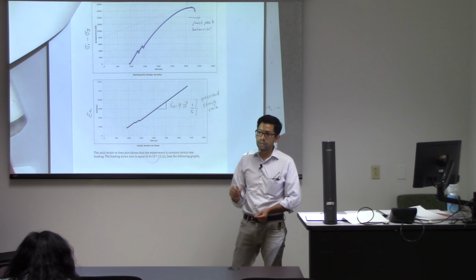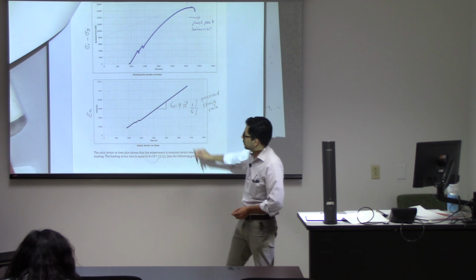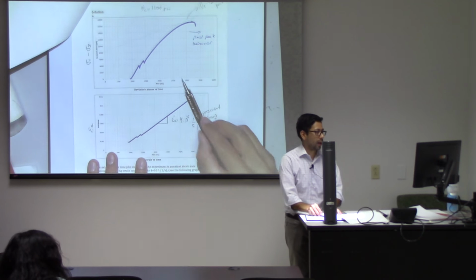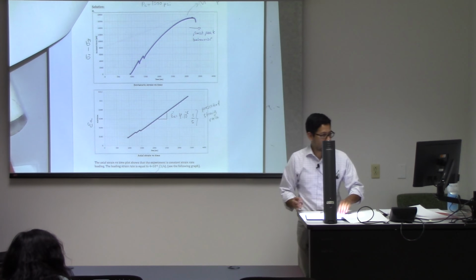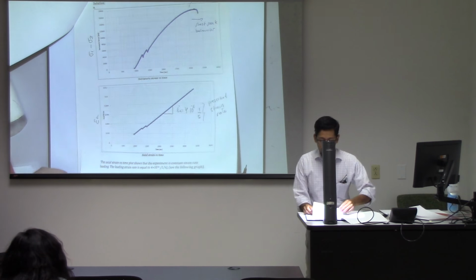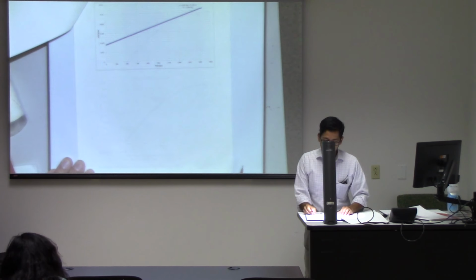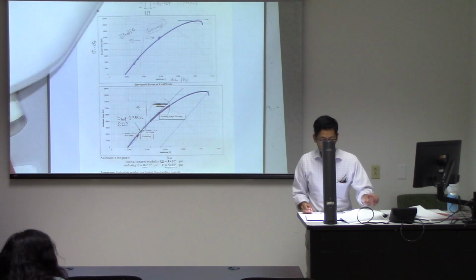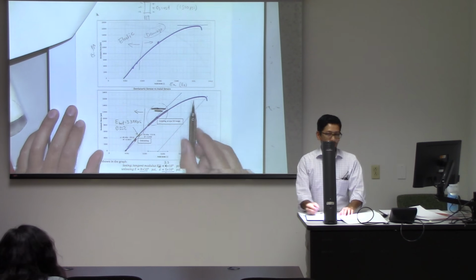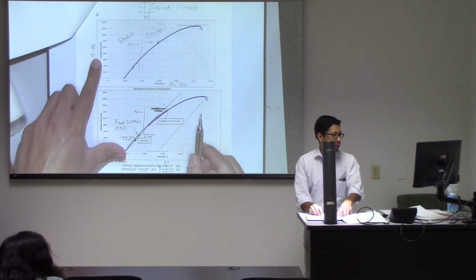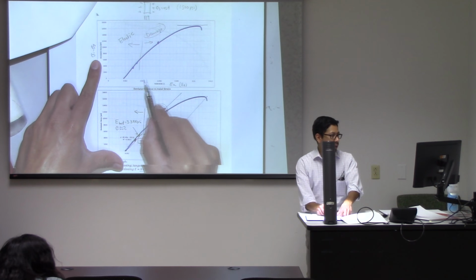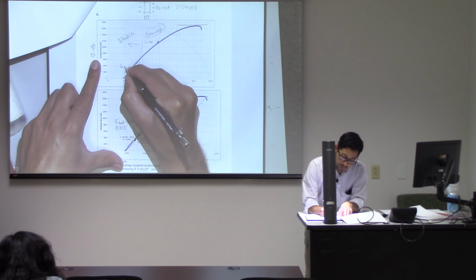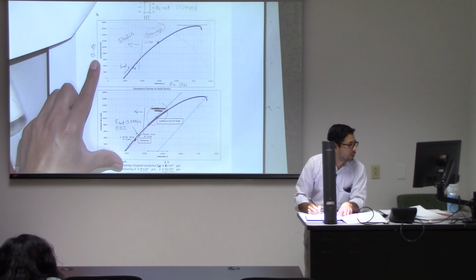But something very important for you to remember is that in many of these tests, you set the strain rate or the displacement rate, and you measure the stress. Let me continue with this. This is just a calculation of the strain rate with linear regression. Now, if we get rid of time and plot deviatoric stress as a function of axial strain, you get this curve. So this is the loading going up. This is the unloading going down.